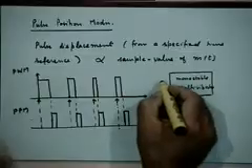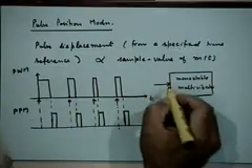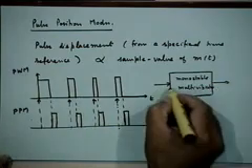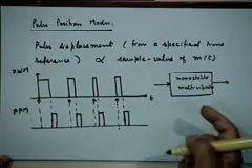A monostable multivibrator is like a flip-flop, except that it has only one stable state. So when you trigger it, it goes into an unstable state, and after some time it comes back to the stable state. That's what a monostable circuit is. I will not go into the circuit here because this is not a digital circuits class, but that's what a monostable multivibrator does. So you have a trigger here, and the trigger will make it go into the unstable state.